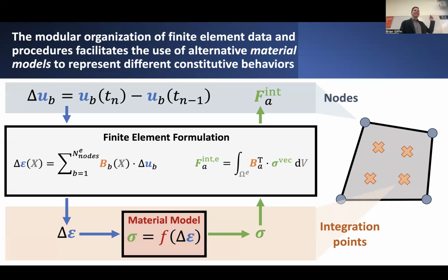And given that increment in displacement, we can then formulate the corresponding increment in strain for the current load step. We can use our standard strain displacement operator to figure out how these increments in displacement relate to corresponding increments in strain. And we can then determine the increment in strain at each one of the integration points inside of one of these elements. So at this point, we've taken some quantities at the nodes, used our finite element formulation to construct our strain displacement operators, and then we spit out some values of these strain increments at different interior material points or integration points within the element.